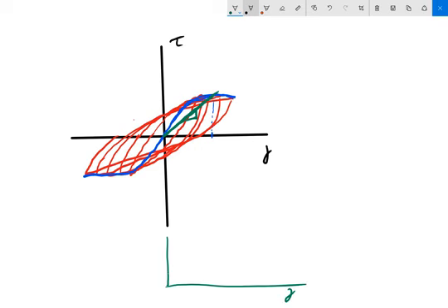So there's gamma again. If we take that same strain value, and this is G over G max, where again G represents secant modulus. So if the slope of that line is, say, G1, then for this point, that's going to be equal to G1 over G max.